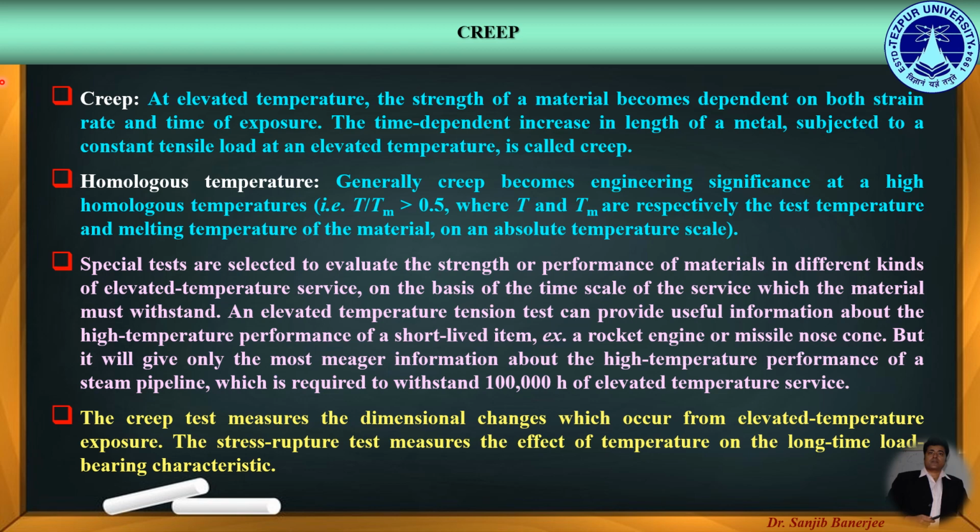A number of metals under these conditions behave in many respects like viscoelastic materials. Thus, this time-dependent increase in length of a metal subjected to a constant tensile load at an elevated temperature is called creep.